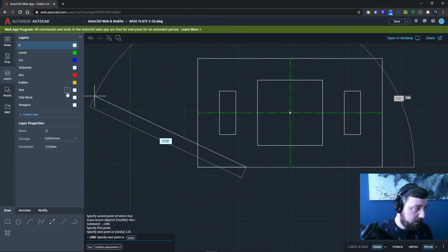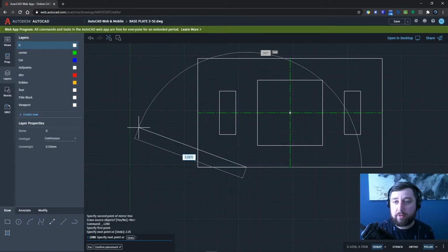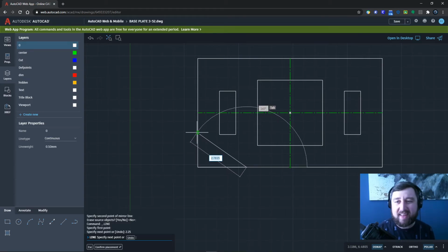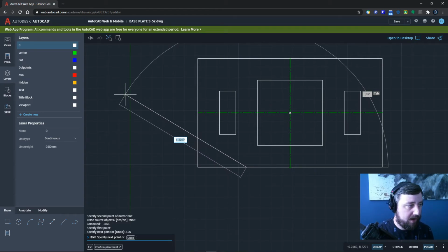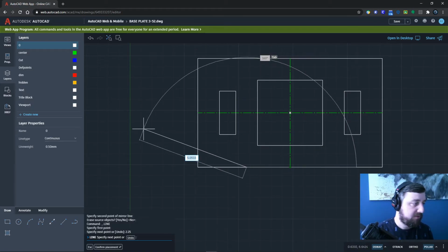At this point, I can go up. And the length of this line doesn't matter. We're just going to trim it. All we care about is the angle. I could mouse over to this, but it may snap to that instead of letting the angle be correct. So I'm going to keep my mouse just out in the distance because it doesn't matter.